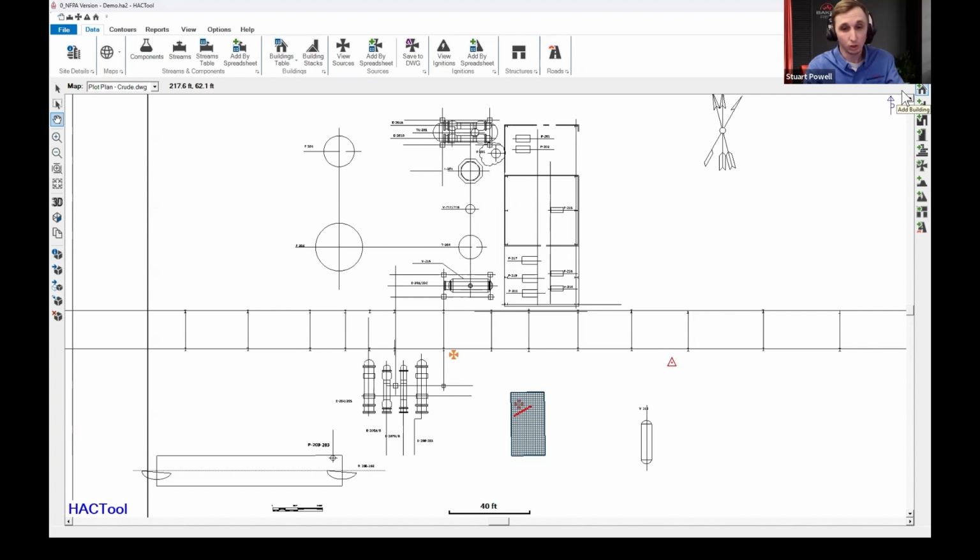And those buildings serve as a potential boundary. So if you have a classified area in the building and you know your walls are vapor tight, you don't want that classified area boundary to draw outside of the building because the wall would confine the classification. And so the building allows you to play with the geometry and adjust based on your specific application.